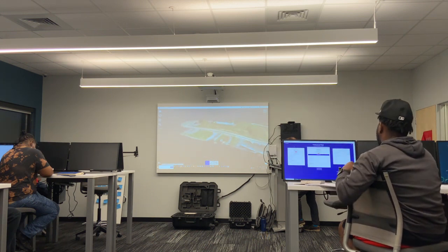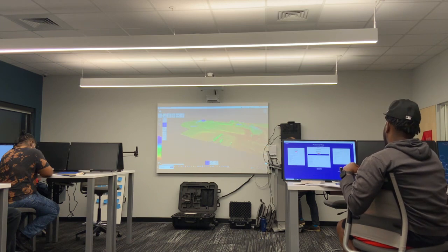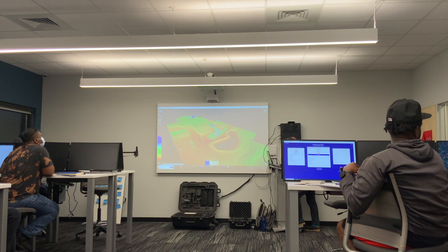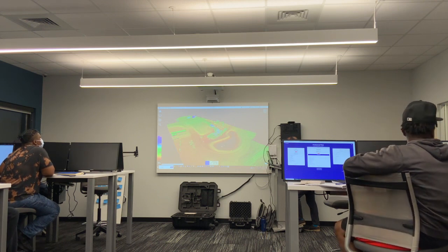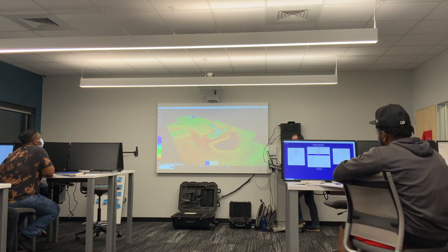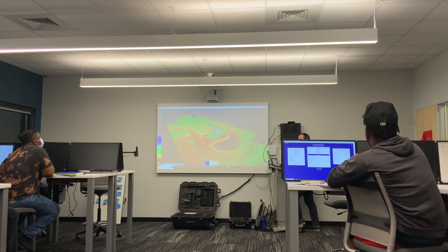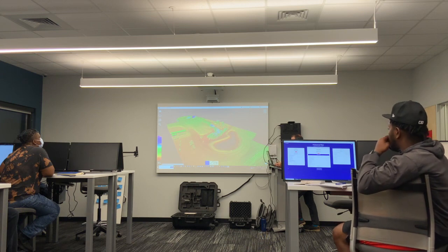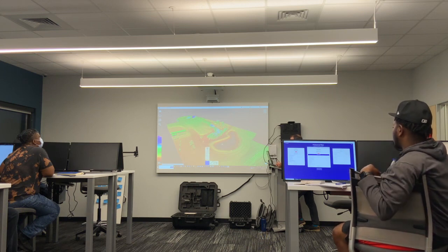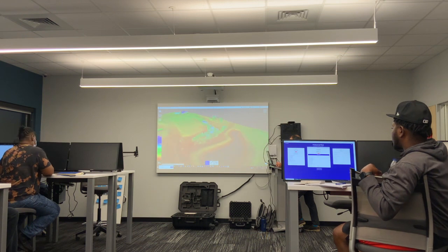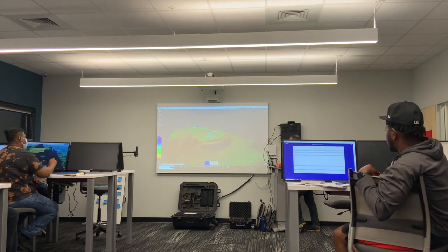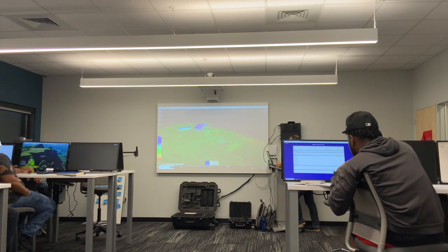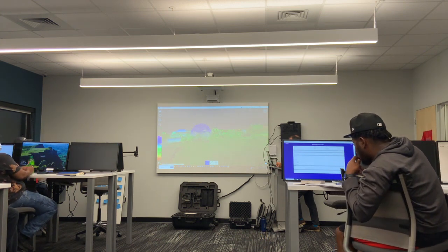So you can do different things with this. Start looking at the elevation. You can see here where there's no returns, no points. That probably means there's water there, because when LiDAR hits water, the laser essentially doesn't come back to the sensor, and so it shows as a gap. We can also tell how tall trees are. So if we're looking for the tallest tree where lightning's going to strike, it's probably going to be that tree, more likely than not.